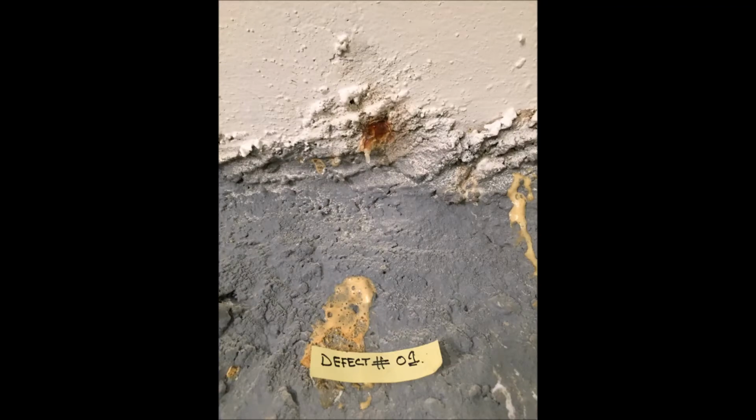Efflorescence is one type of defect found on plaster surface. Efflorescence is the whitish crystalline substance which appears on the surface of wall due to the presence of soluble salt such as sulfate of sodium, calcium and magnesium. However, the root cause could be the presence of salt in the lime, cement, sand, bricks and sometimes even in the water used in construction work are the cause of efflorescence on plaster surface. The crystals like ice are deposited as you can see in the video.